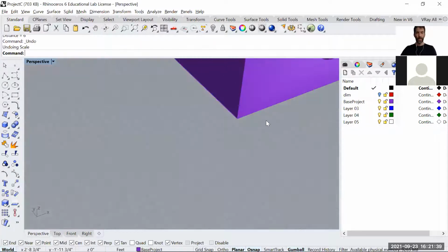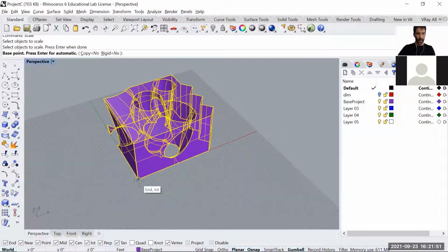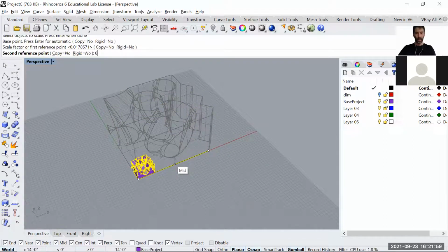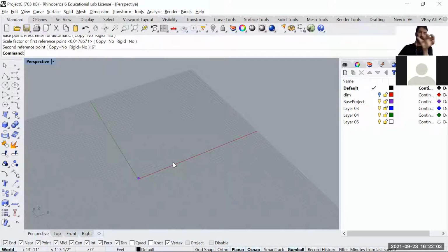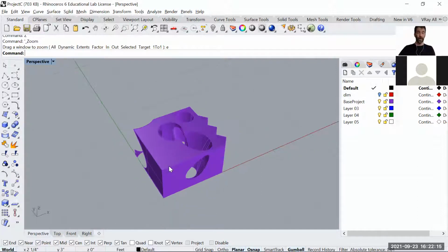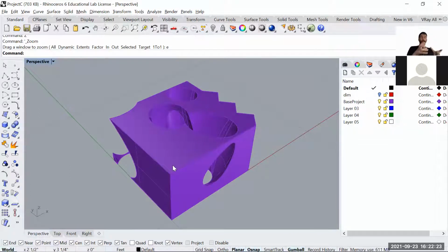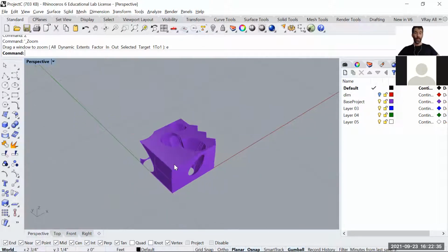I'm going to do it again, Control C. If you know one dimension precisely, of one of the sides or one door, one stair, you can always scale your model from this, and it's a reference scale. So you say from here to here, this is the dimension I know. Let's imagine it's 6 inches. It reduces that dimension exactly to 6 inches. And maybe this is a 6-inch 3D printed model. Maybe it's a little bigger, maybe a little smaller, whatever it is, but it makes sense. Again, we can't do the entire building. So after scaling down, that's when you do the laser cutting process. You can scale down the drawings, if you create the exploded elements, by factor or by dimension, also the lines, with no problem.